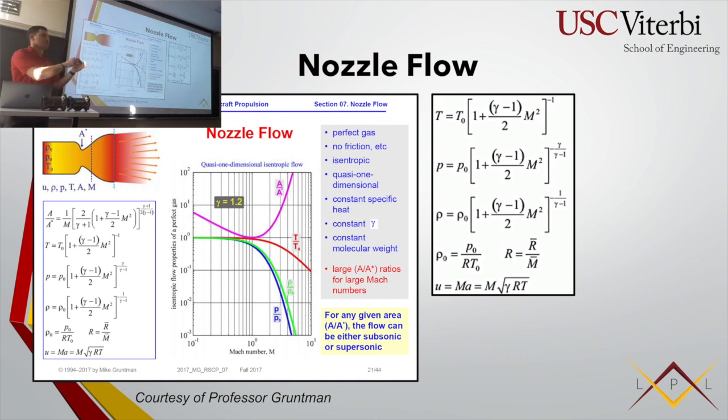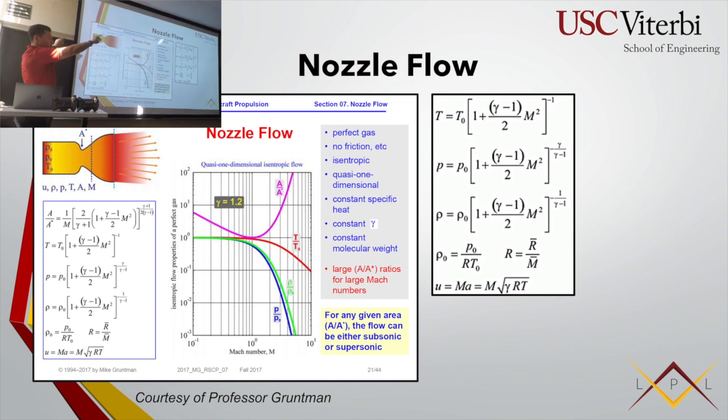And then you'll notice, like if you watch a SpaceX video, the plume just becoming huge, versus not. And so that has to do with that. It's not too critical, but you just won't have the best performance, right? You might have losses due to the flow coming off the wall because it doesn't have enough pressure, and you'll have certain shocks generate, or if you have an overexpanded nozzle, that's where you see the Mach diamonds, right? The famous Mach diamonds.